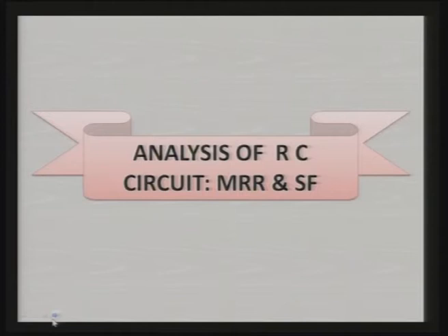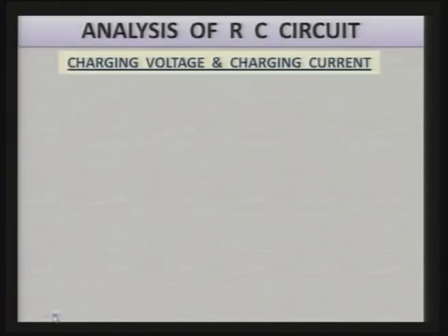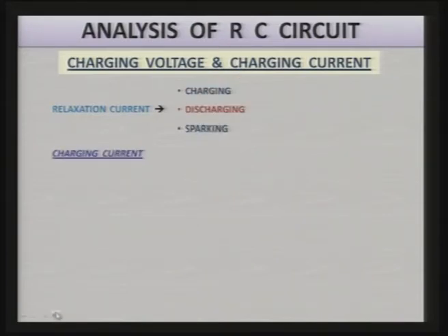Let us see the analysis of the RC circuit and how to calculate material removal rate, how to calculate maximum power delivery to the discharging circuit, and surface finish, especially in case of the RC circuit. Now, this is also known as the relaxation circuit, and you have the 3 phases of charging, discharging and sparking, which I will show you in the diagram.